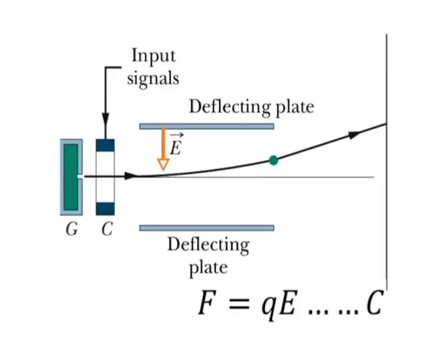In practice, E is held constant and the position of the drop is determined by the charge Q delivered to the drop in the charging unit, through which the drop must pass before entering the deflecting system. The charging unit in turn is activated by electronic signals that encode the material to be printed.